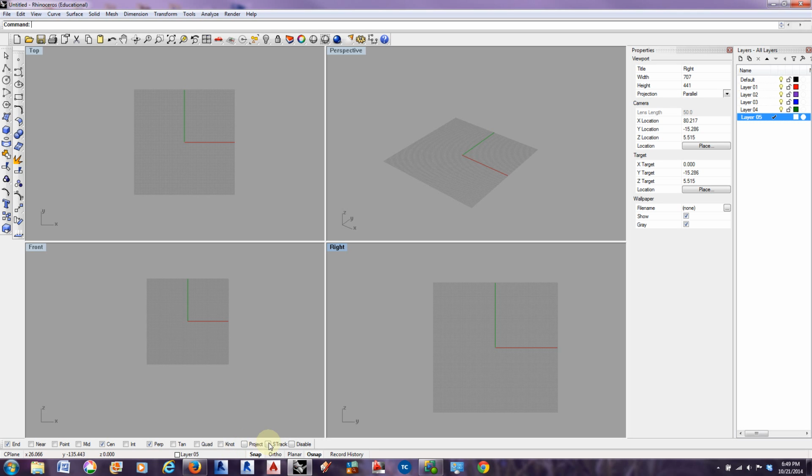Sorry. At any rate, you can leave that up, and at some points you may want to disable it for some reason, similar to disabling the O-snap in AutoCAD. It turns it on and off. S-track is the smart track, so you can disable it or turn it on here as well.